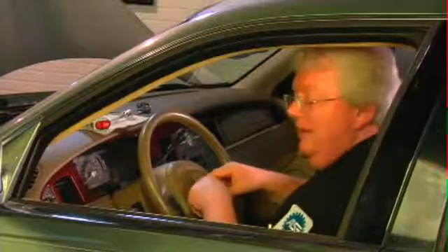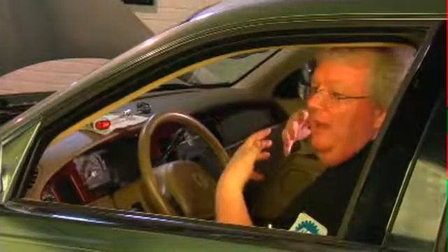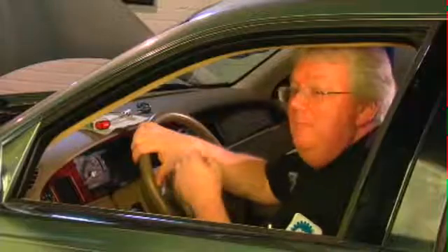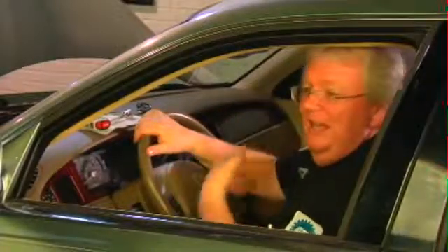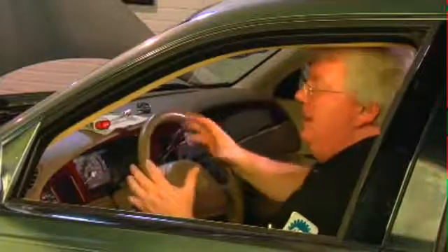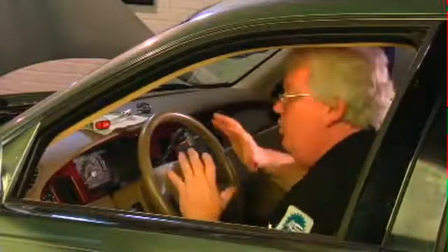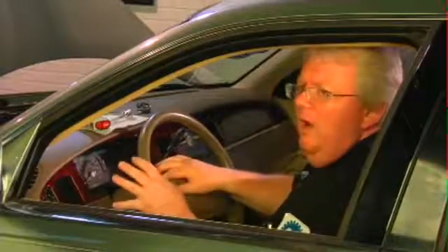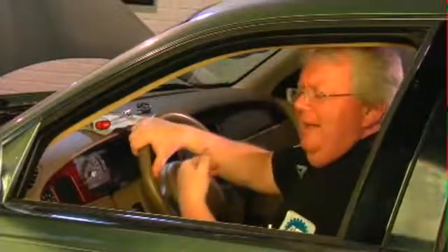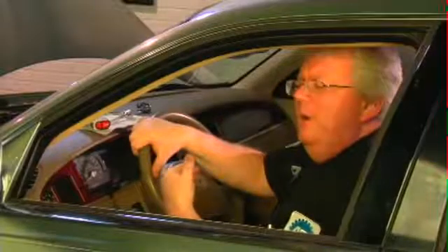is going to make the chemicals in this airbag begin to burn and rapidly, within a few milliseconds, we've got this huge pillow in front of our face, which while it will deflate immediately, which is part of the absorption that an airbag does, absorption of energy, kinetic energy, but the force of it coming forward, if you were to be working on it, have a tool in its way, and for some reason it were to go off, now that may seem to be a little overkill, but let's think about it.